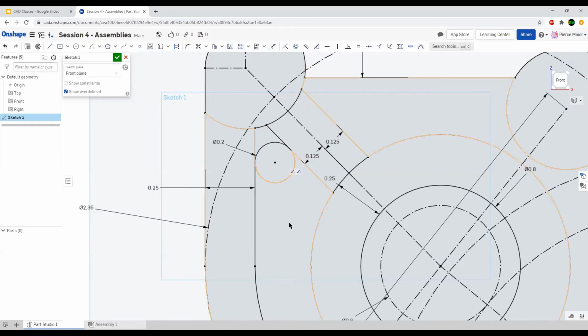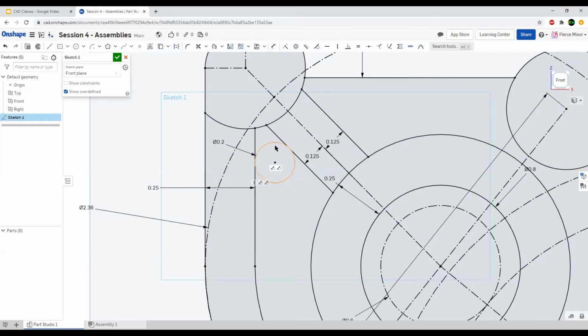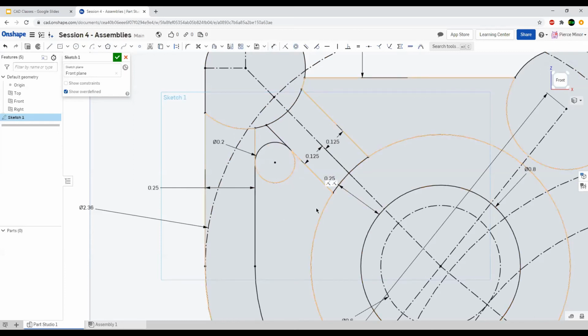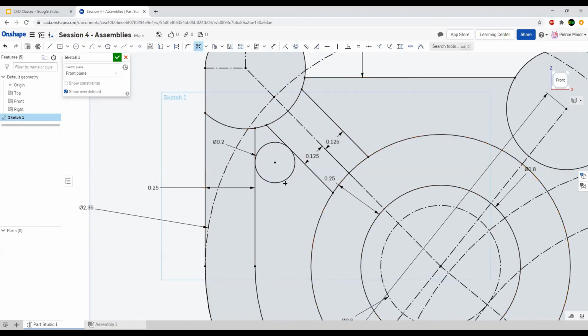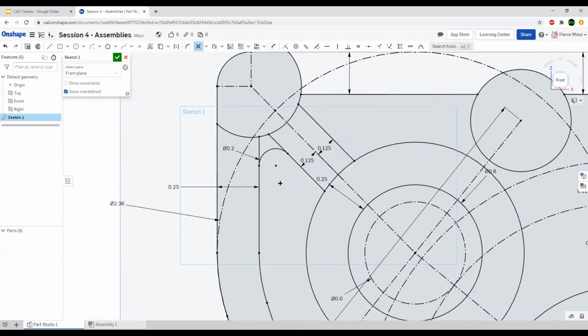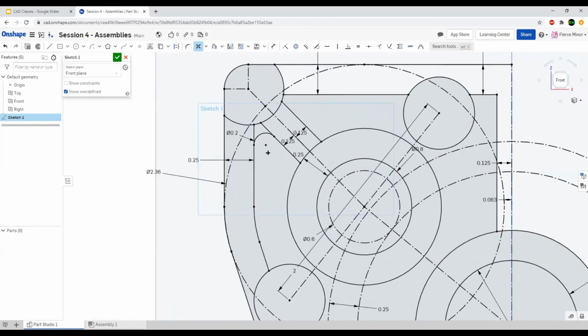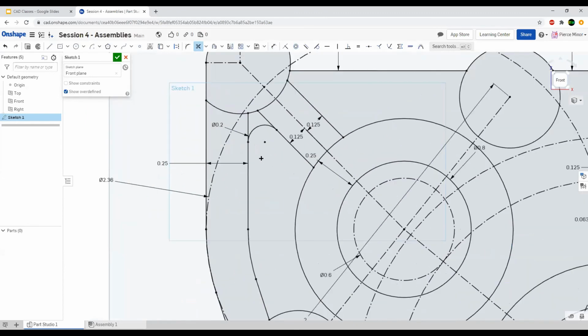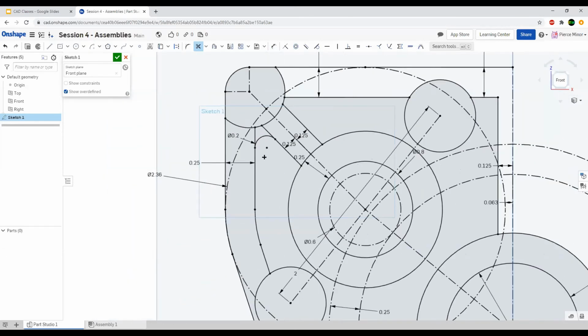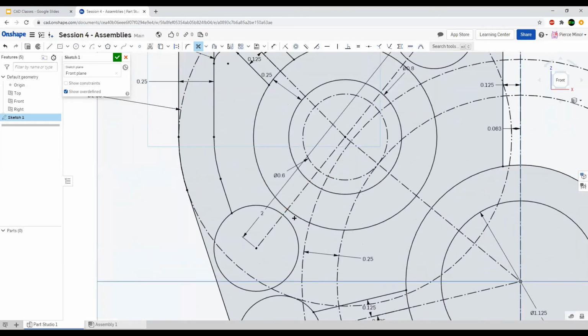But the problem here is, okay, it's a circle, but there's all this curve. I don't need that. That's where the trim tool comes in. Again, you can just trim off that side and look, you have a nice rounded curve. It looks super nice. It's very pretty. So now, see how large that curve is? See how small this gap is?